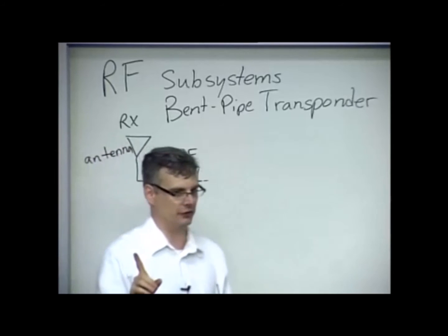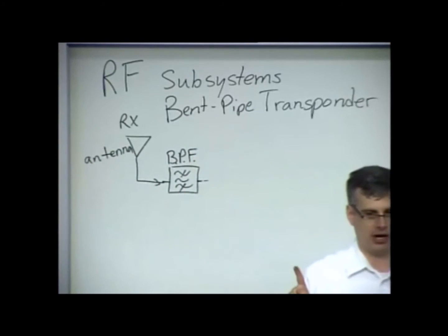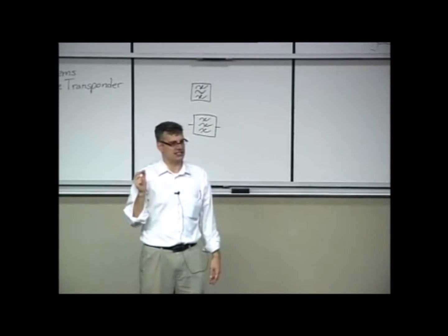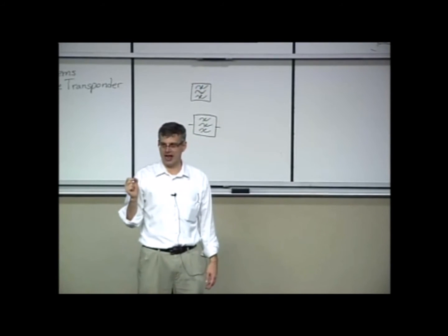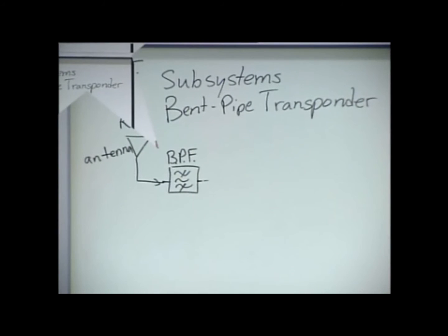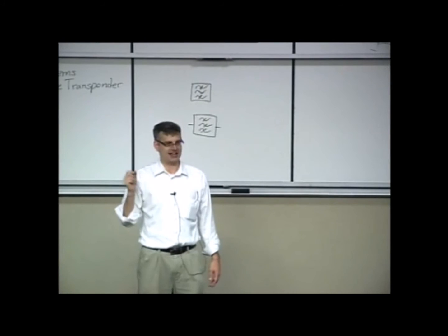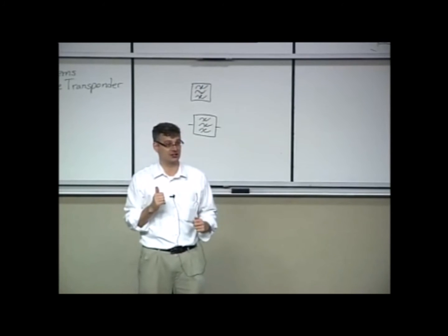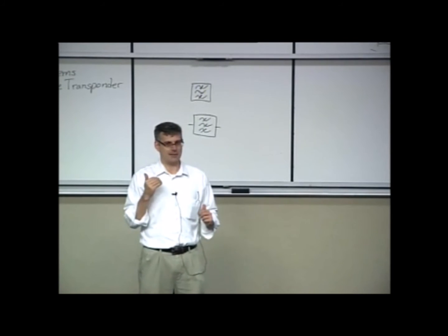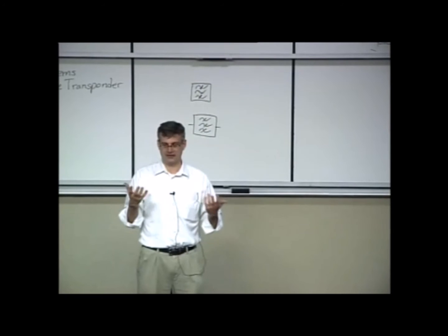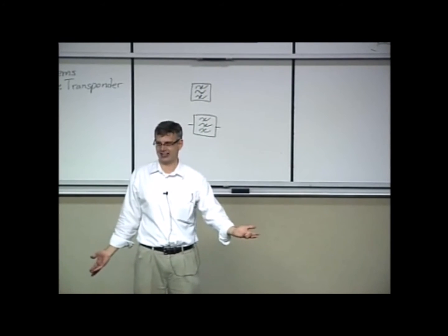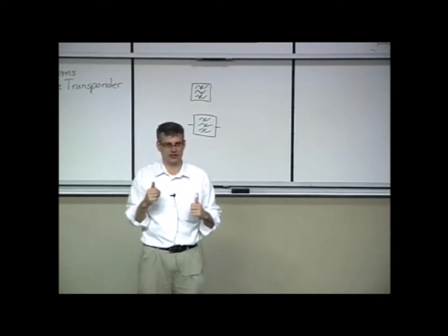I say a little bit of filtering because you don't want to put too much there. When we do noise analysis of the RF chain, we'll see why. This is where the signal is the most fragile. The signal-to-noise ratio is the highest it can possibly get at that point. Anything you do to it, you have to be careful, because anything you do to it is going to degrade that signal-to-noise ratio. A passive bandpass filter will not add any signal energy. It can only really add loss, which will degrade the signal-to-noise ratio.